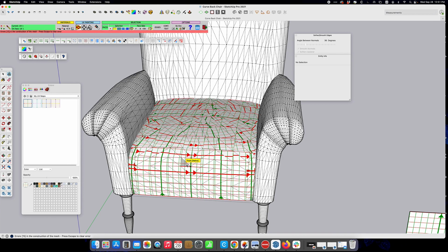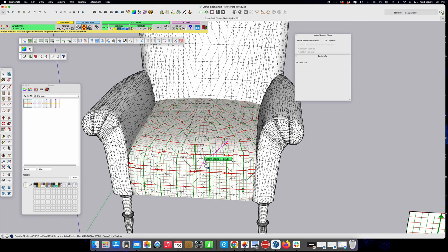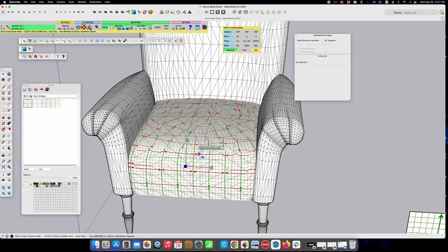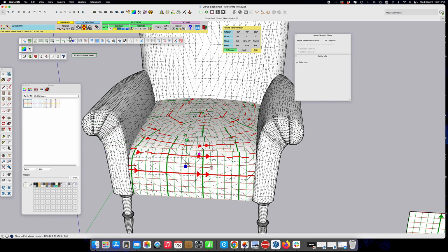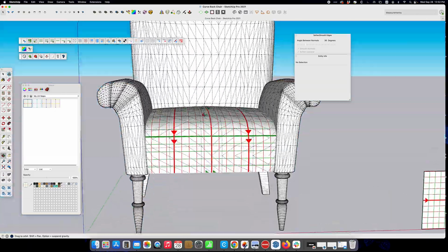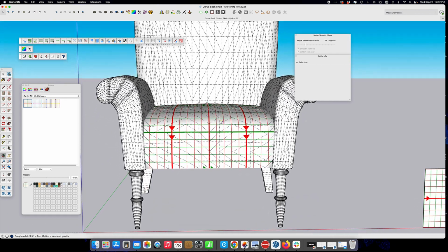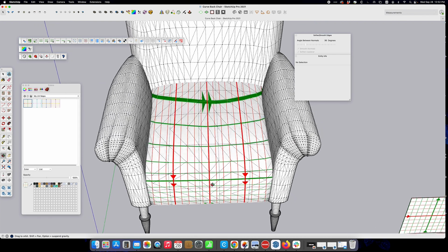So if I try to click on this and I go here, everything is lit up red, and it's saying that it doesn't really work. If we choose the natural UV and we click on, that's not really working too well either. And then if we click on projected, that looks a lot better. You can see that the texture is going across all the surfaces, but projected acts as if you're putting the texture on from whatever angle you're looking at.